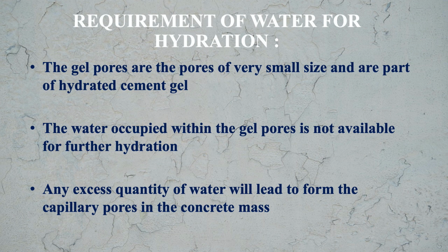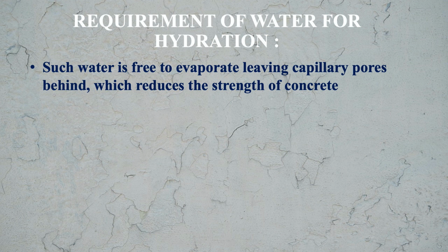Any excessive quantity of water will lead to the formation of capillary pores in the concrete mass. Means the water which is required for the hydration process, if you are using more than this quantity, then it will lead to formation of capillary pores in the concrete mass. And such water is free to evaporate, leaving capillary pores behind, which reduces the strength of concrete. Means this excessive water will be evaporated and it will leave the capillary pores in the concrete, and that way it will weaken the concrete.